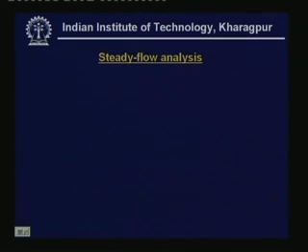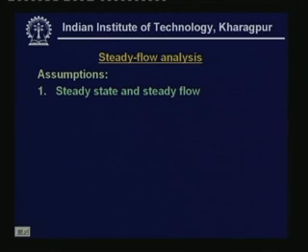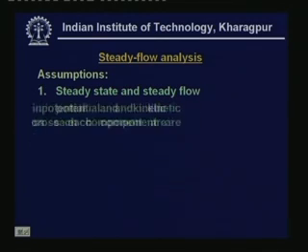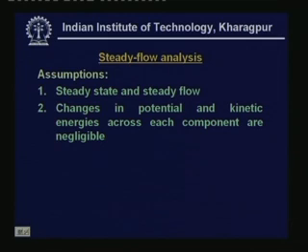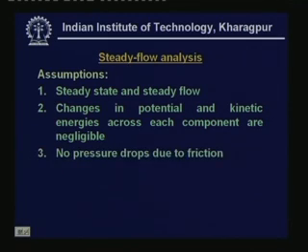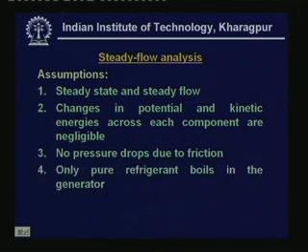Now let us look at steady flow analysis of a simple single stage vapor absorption refrigeration system based on water lithium bromide. First let me list out the assumptions made. The first assumption is the usual assumption, it is a steady state and steady flow process. Then changes in potential and kinetic energies across each component are negligible, and there are no pressure drops due to friction, and finally only pure refrigerant boils in the generator.